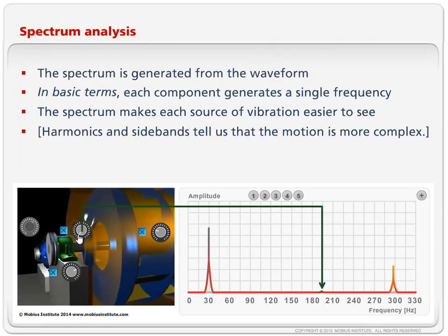Because while we're monitoring the condition of this machine and we've got this unbalance, we damage the bearings. That's one of the root causes of bearing failure, misalignments and unbalance and these sorts of faults. So now we've seen the bearings start to fail. The patterns are a little bit different to this, but you get the principle. So we'd like to know something about the machine, so we know its running speed, something about the bearings, something about the fan. So that's the basic idea of spectrum analysis.